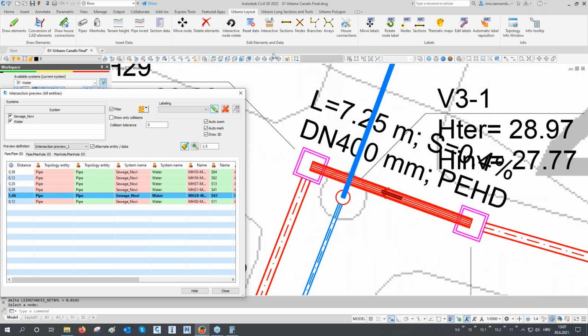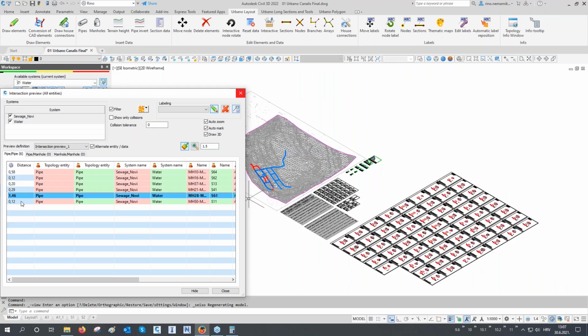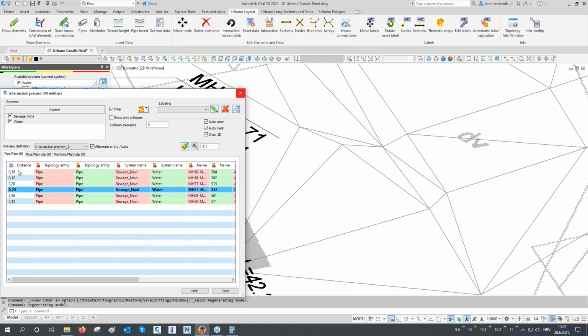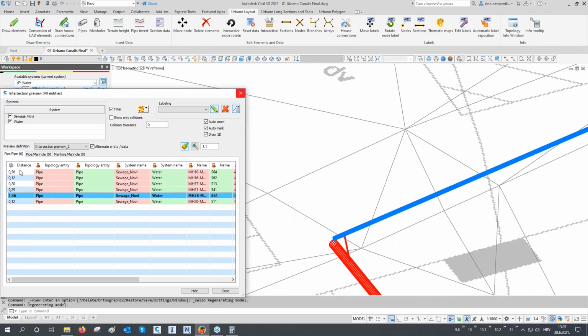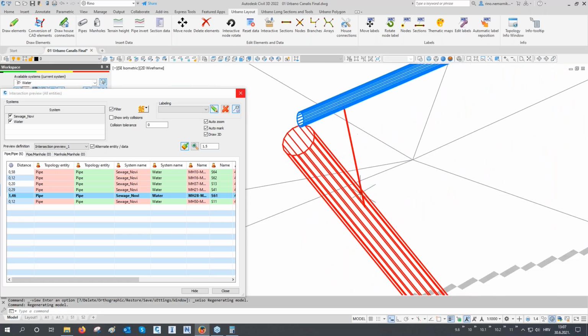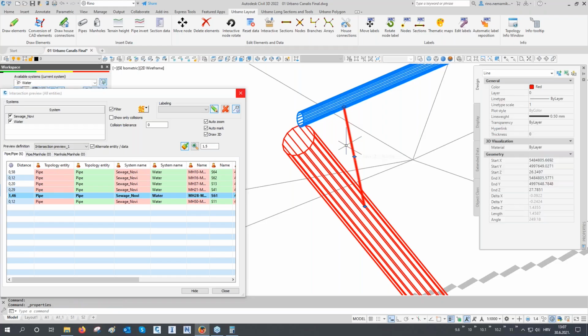If you switch to the 3D view in AutoCAD, we can see that the software is searching everything and calculating the distances between the two closest 3D faces. So this is the distance. If we open AutoCAD properties and check the length of this shortest distance, this is it. This is the length of 145.146 that is being shown here.